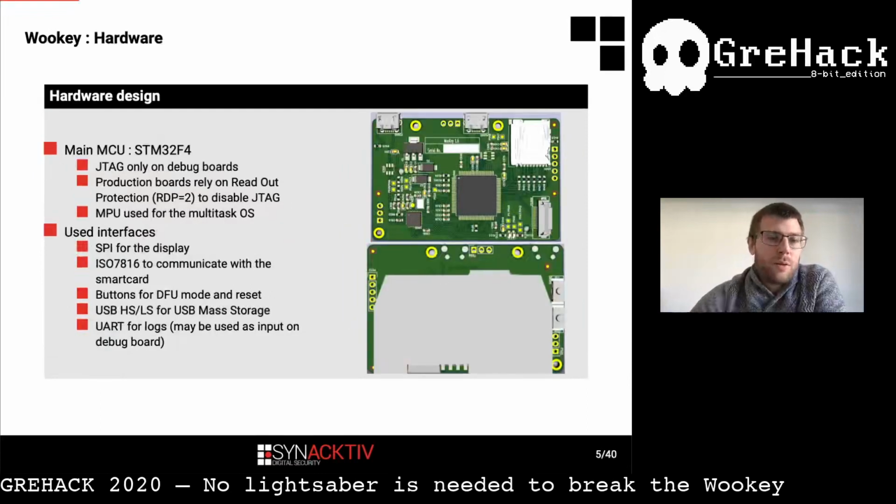Wookey is based on the STM32F4 MCU. It has a JTAG on debug boards, and it's disabled by STM32 protection on a production board. The memory protection unit is used to implement a multitask operating system, and several interfaces are used.